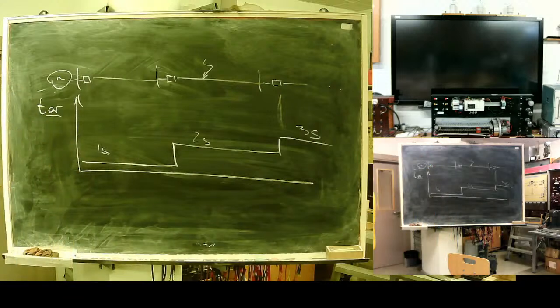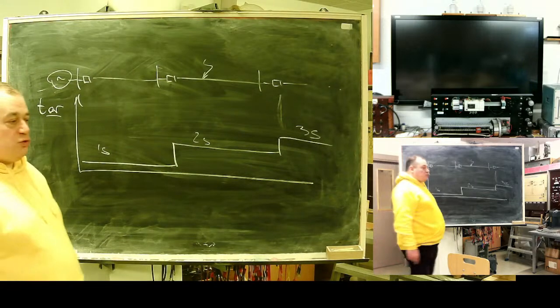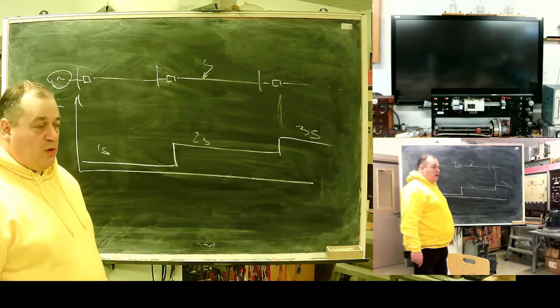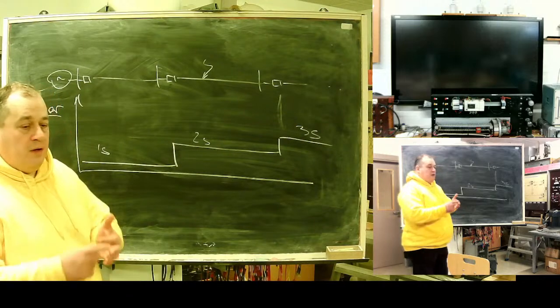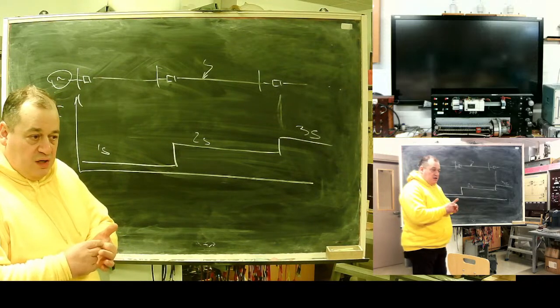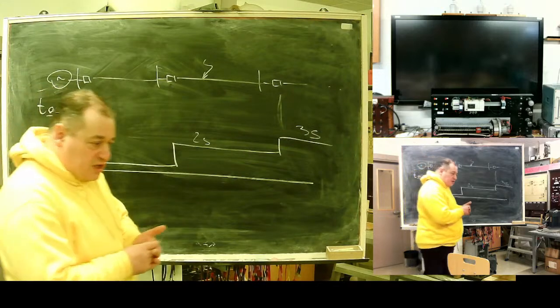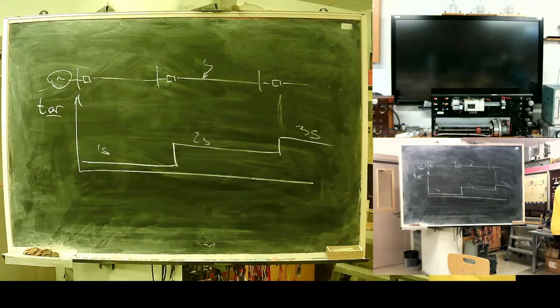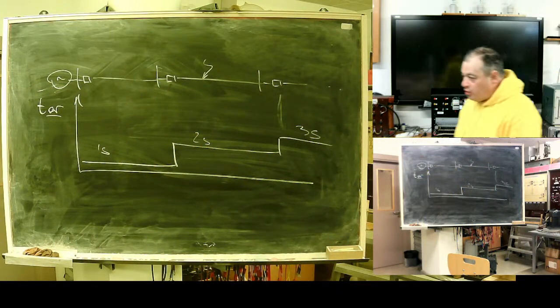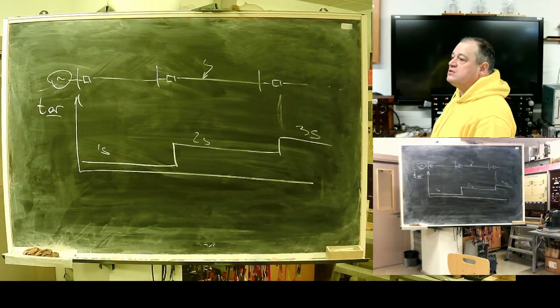For reclosing logic, the number of operations should be limited. One or two, two is enough. The third one will be when the dispatcher tries to switch the line on. So, operation only if disconnection was by protection signal, and a limited number of operational tries. That's what we needed. Now I can start to speak about the inner logic of reclosing.